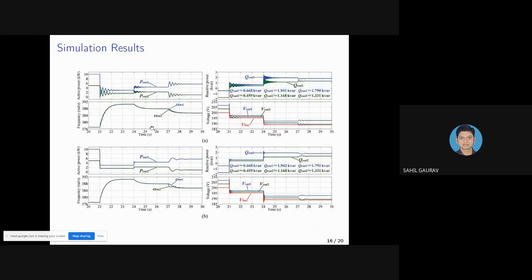So if we compare A and B, we can see the oscillation has largely damped out in the second case because of the stator impedance adjuster. Because we enable it in the inverter control, it gives proper active power sharing during transients and damps out the oscillation of active power sharing. So it easily works in good condition.